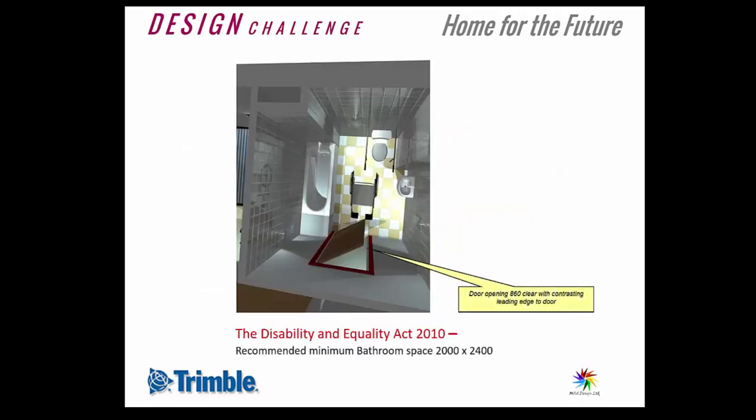If we look at what the requirements are for a bathroom, as I say, the space is 2,000 by 2,400. We need to make sure that the door has an 860 clearance.